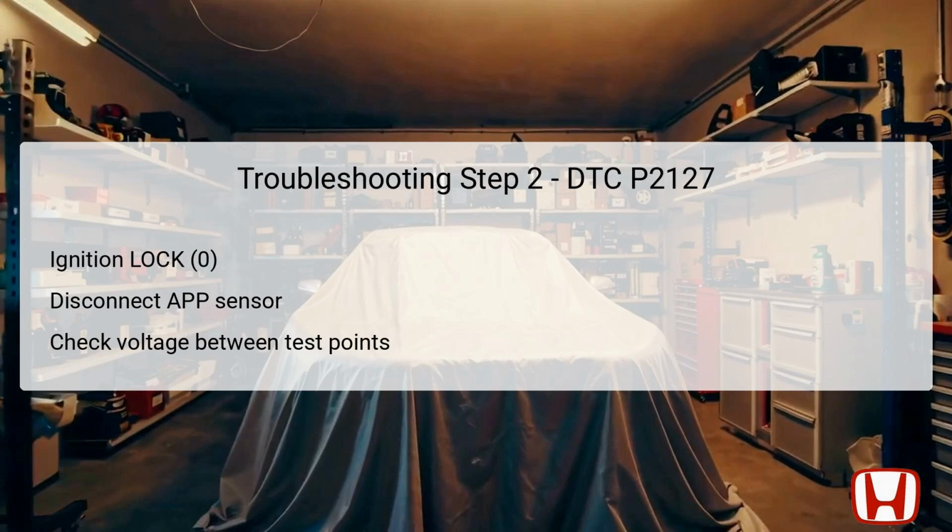If the voltage is approximately 5.0 volts, this indicates a proper supply voltage, allowing you to proceed to step 3. If the voltage is not approximately 5.0 volts, you should move on to step 6, where further diagnostics will be performed to identify the underlying issue.